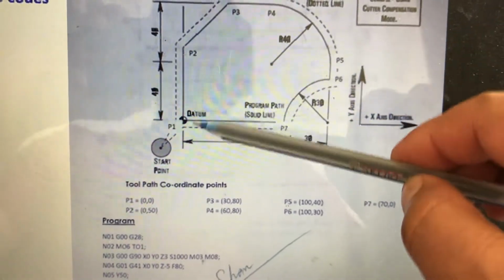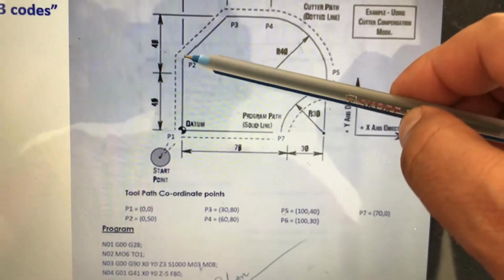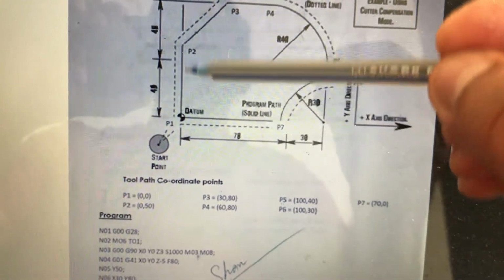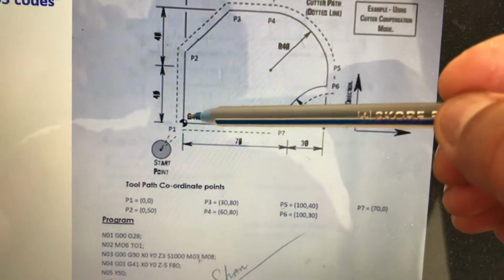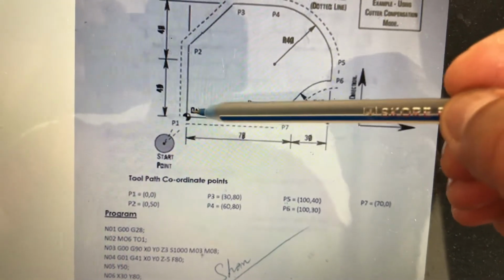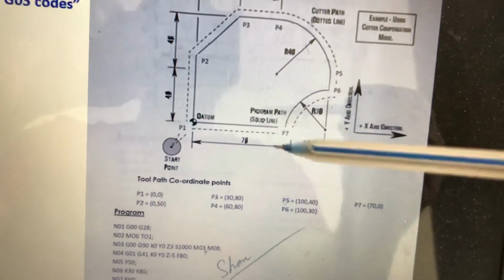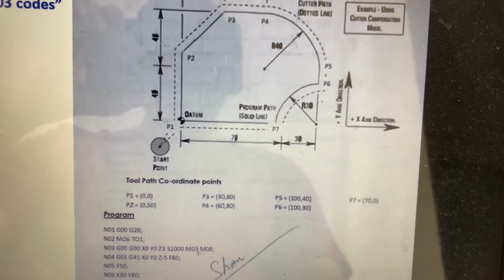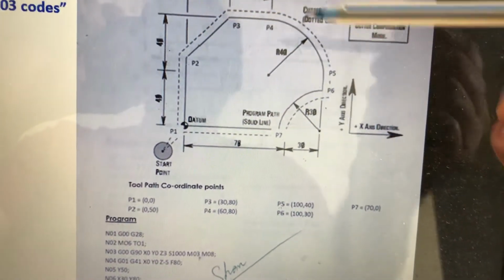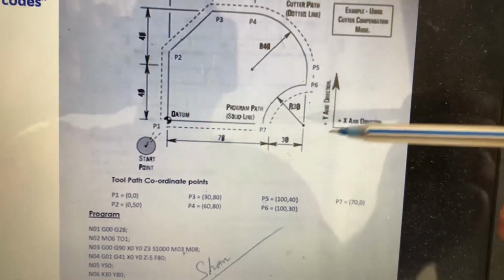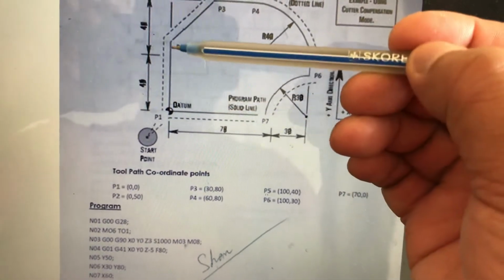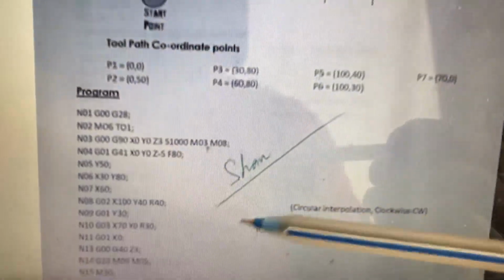So when you're cutting here, we should use the tool nose radius compensation, because if you say G00, the tool is exactly here, you cannot move. If you are cutting like this, the radius of the tool will cut into the workpiece, so we have to adjust for that radius. So we should give the code G41 or G42. Since the direction of cutting around the profile is clockwise, we will use G41 as the tool nose radius compensation.